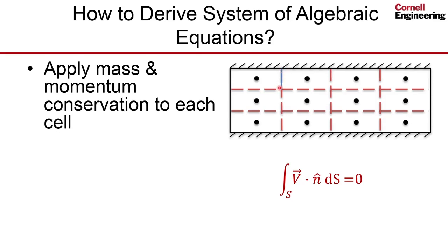Now I need to know what the velocity is over there to figure out what the volume of flow going out is. I'll assume that the velocity along this segment of the control surface is constant and equal to the value at the midpoint. So I'm doing averaging here, and I'm introducing an error in the process. This value is not calculated directly, so we have to use an interpolation between the cell center values. So we just interpolate these two cell center values to get that.